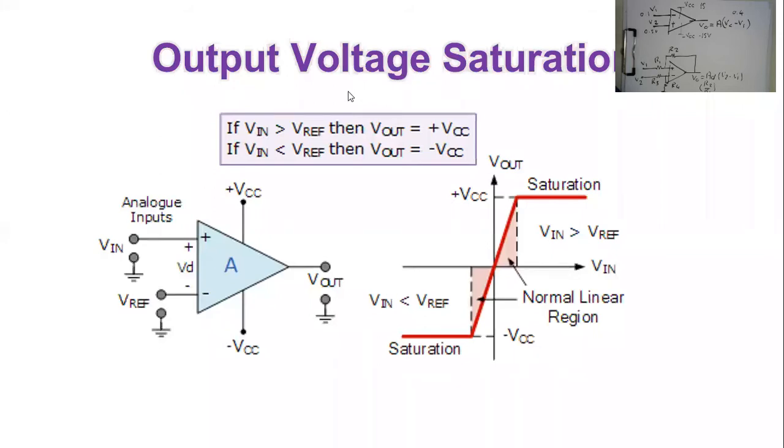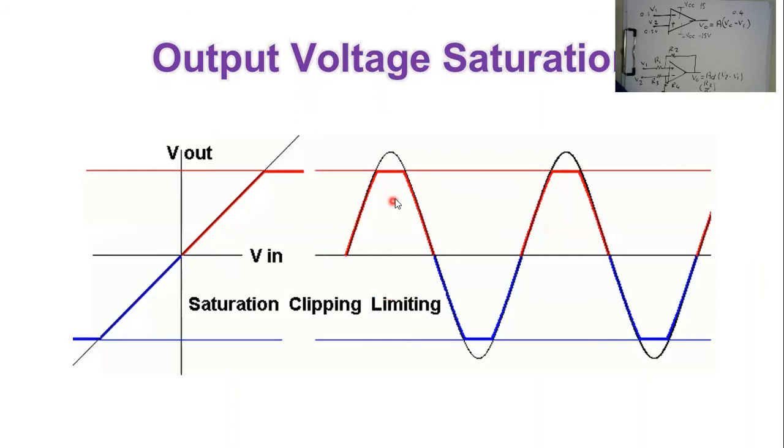Again, let's open the pointer. Now this is the saturation level. As you can see, this range is from negative VCC to positive VCC. So your gain is granted whenever it's in this range. However, whenever you go above or below this range, you will have a saturated output, and this is basically the saturation. You can see it here, this clipped sinusoidal signal, because it's outside the linear range. So it is now in the saturation range, or what's called the output saturation.